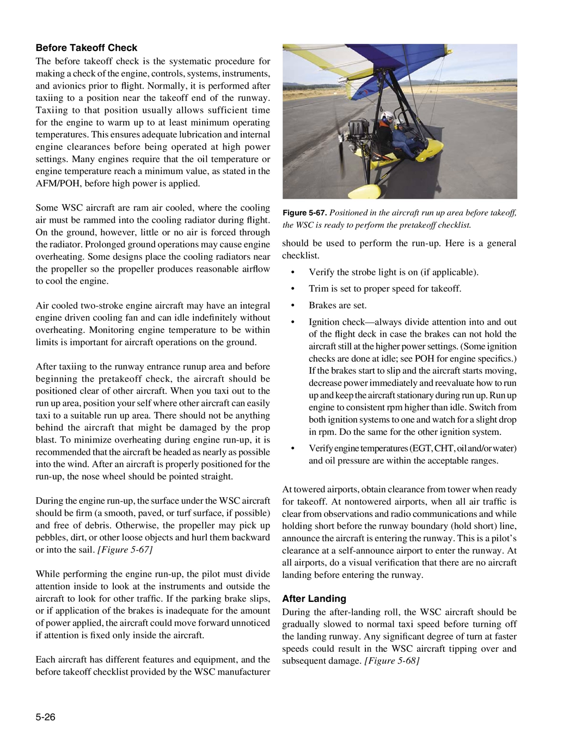Figure 567. While performing the engine run-up, the pilot must divide attention inside to look at the instruments and outside the aircraft to look for other traffic. If the parking brake slips, or if application of the brakes is inadequate for the amount of power applied, the aircraft could move forward unnoticed if attention is focused only inside the aircraft. Each aircraft has different features and equipment, and the before takeoff checklist provided by the WSC manufacturer should be used to perform the run-up. Here is a general checklist.